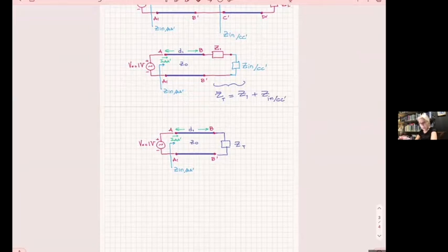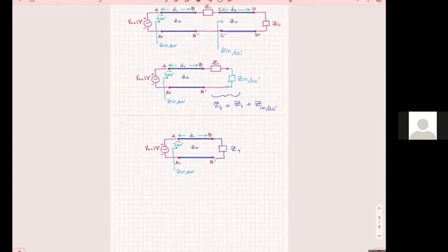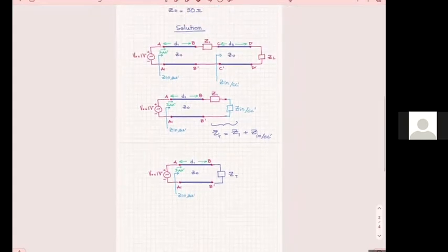You solve it like that, both on paper, and you solve it like that using the Smith chart. So let's try to do this by using the Smith chart to follow this process for the solution. So just to summarize, we're first finding the impedance at C and D, and then the impedance at A and B. Yes.